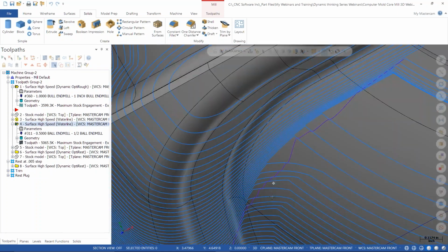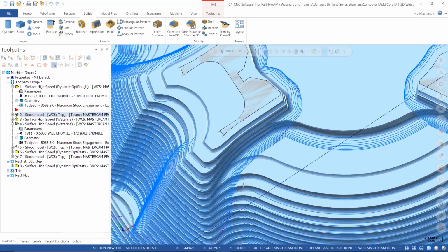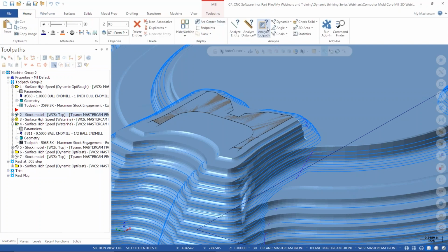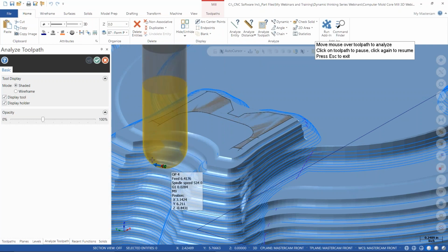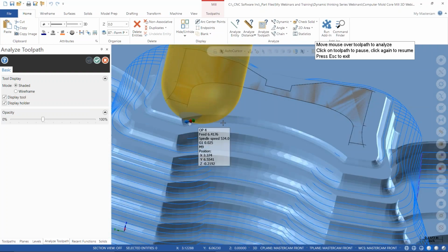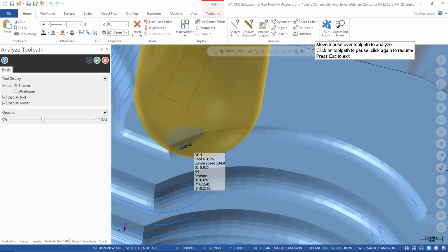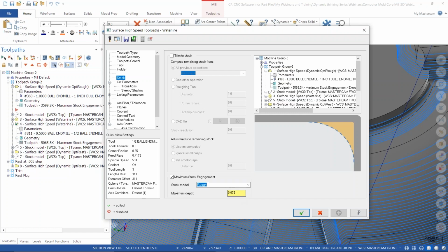And even right here, you can see if I turn this on, and maybe I take my analysis. I love using Analyze Toolpath, and let's get it in somewhere like here on this pass, or this pass here, because that's the top. You can see it's digging into stock, but that's as deep as it went. It's not going to go any deeper than 0.075. This is not a perfect science all around, but this was developed to protect small tooling at times. It's a very niche function.